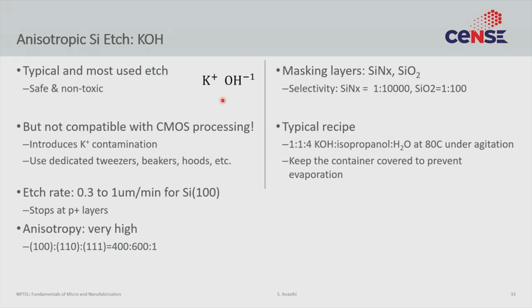So first you do a patterning of the silicon oxide or the silicon nitride using hydrofluoric acid, and then use that patterned silicon dioxide to actually do the patterning onto the silicon. The selectivity you can actually get in this process is also very high. The nitride, for example, the selectivity is 10,000:1. For silicon dioxide, the selectivity is 100:1. So just 100 nanometers of silicon nitride is enough to etch around 100 micron of silicon, right? So that's very deep.